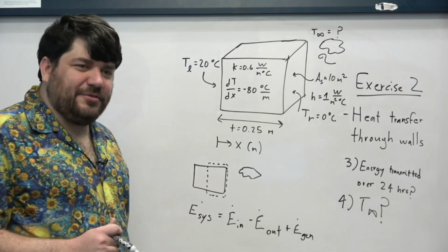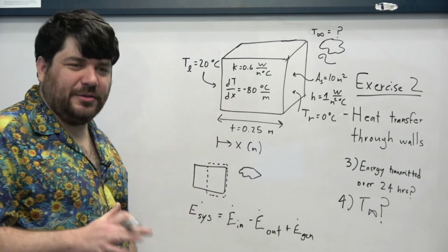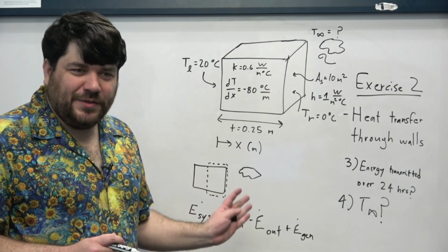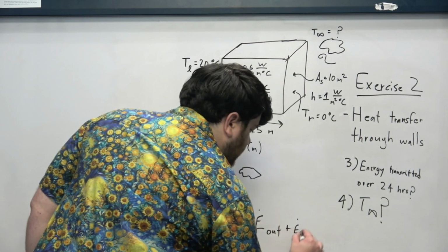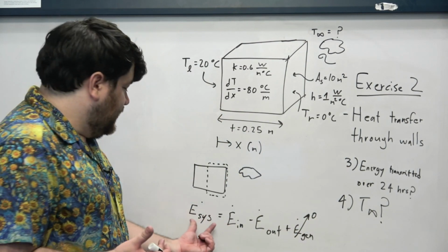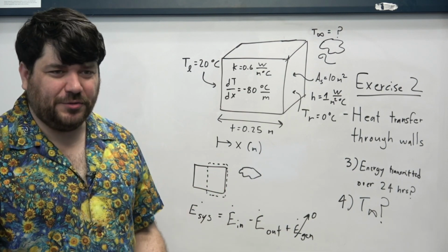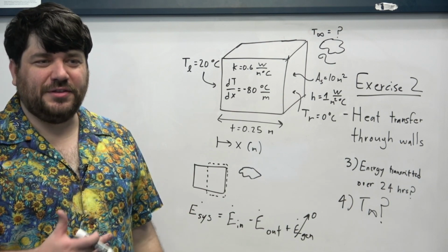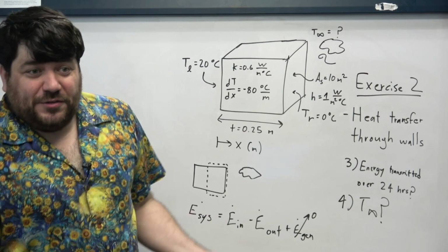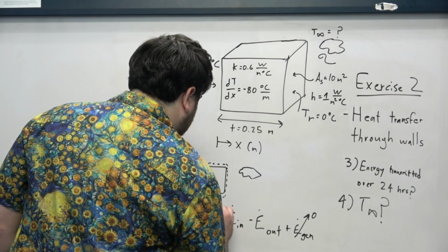Now, is there volumetric thermal energy generation inside of this problem? No, this is a regular, nice, old brick wall. Nothing is happening in here. So there is no internal energy generation inside of this little piece of wall. Similarly, because the system is in steady state, the thermal energy of this region of wall doesn't change because the temperatures don't change. We found an expression for the temperature profile, and that expression does not vary in time because we assumed that it wouldn't. So this is also zero.